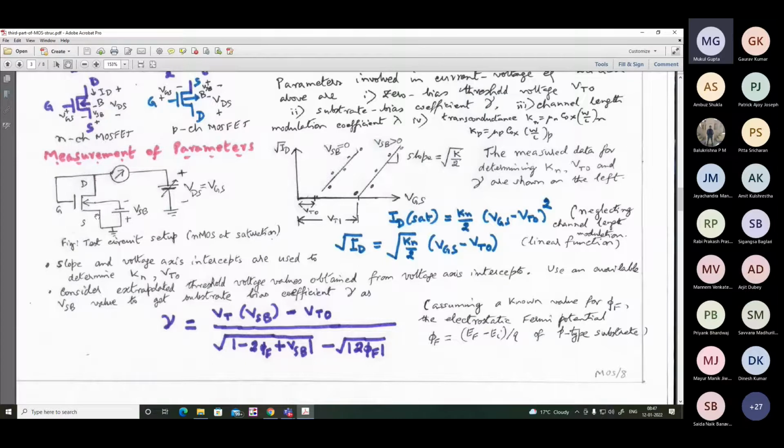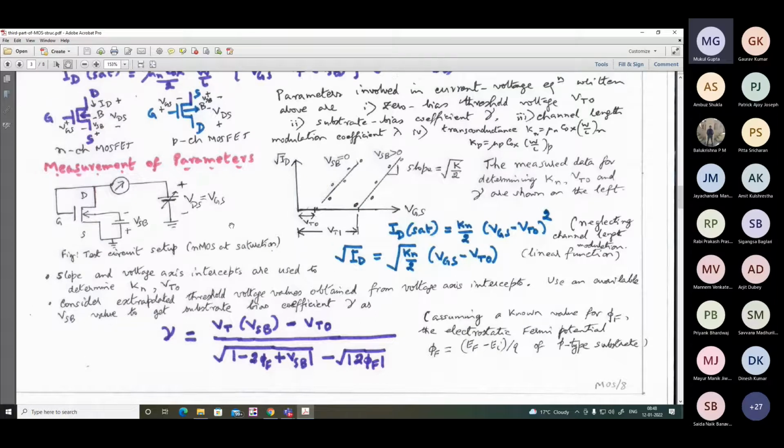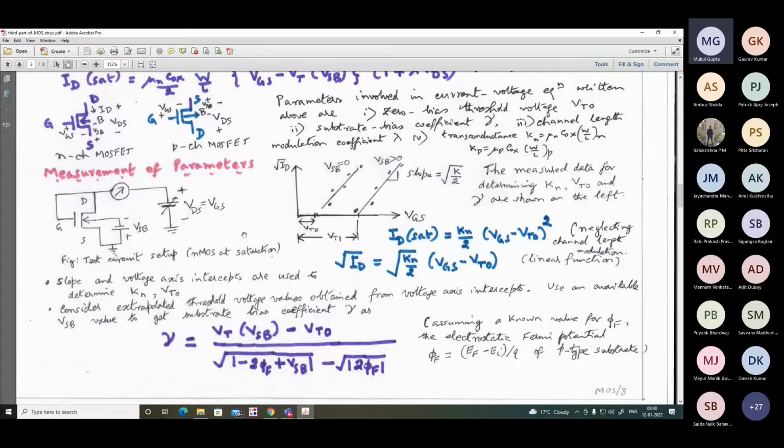So here you also have a means to control the threshold voltage, right? Because you have another potential source here. So if you can make the transistor merely in saturation but not in deep saturation, then you can neglect lambda, right? It's clear, right? So for practical matters, in order that this equation be in force, we make this experimental setup where you can justifiably neglect lambda.